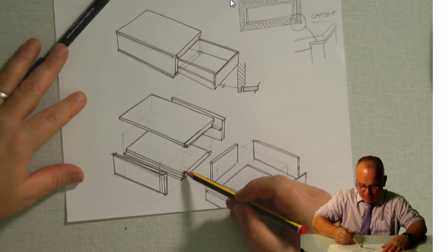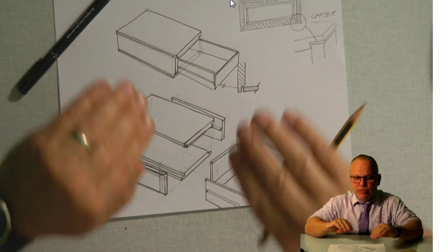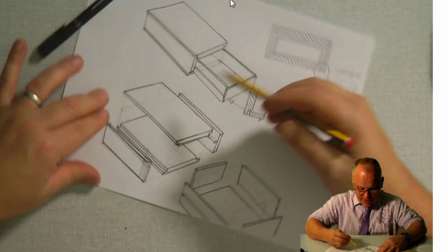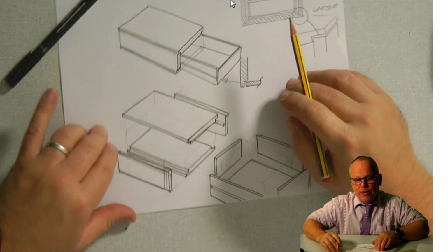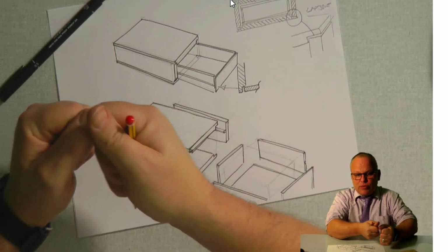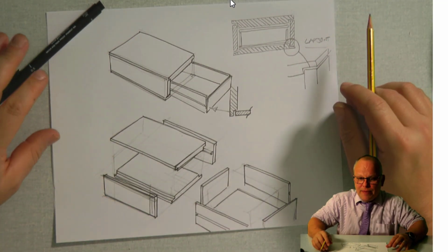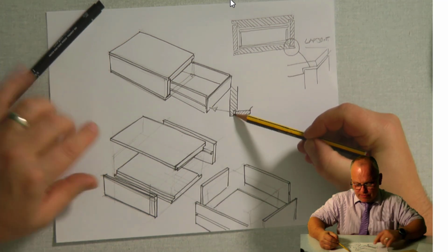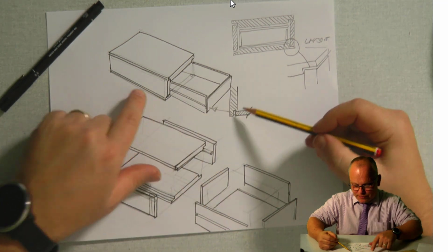I did think about maybe putting some sort of nylon-y low friction bearing runners at the bottom. I think there's probably some sort of stop that I'm going to have to think about at the bottom to stop the drawer from coming all the way out. So I'll do a little bit further investigation on that. But what I am showing here is that at this point I'm showing that that is a lap joint.